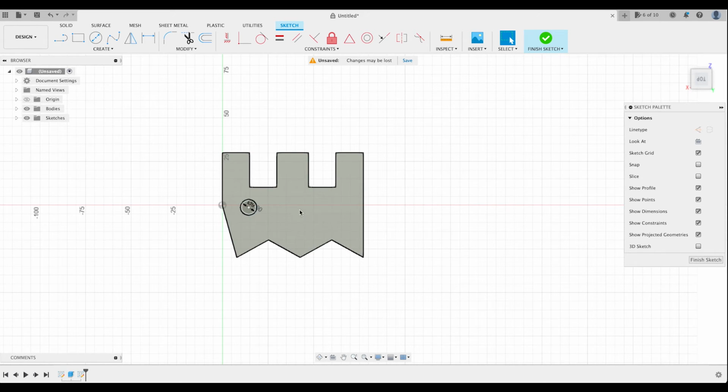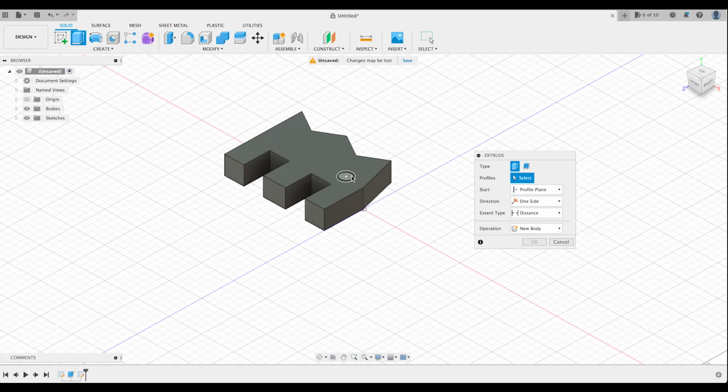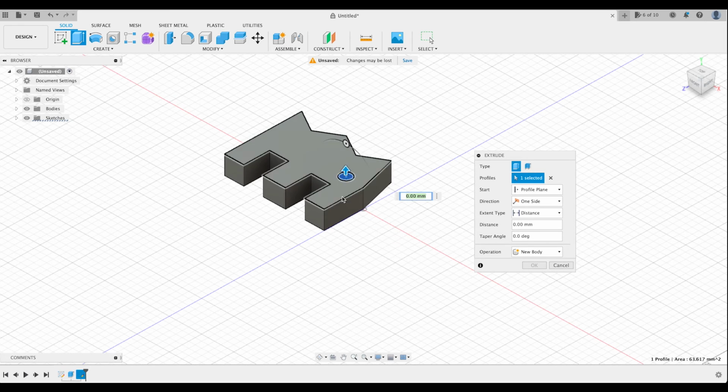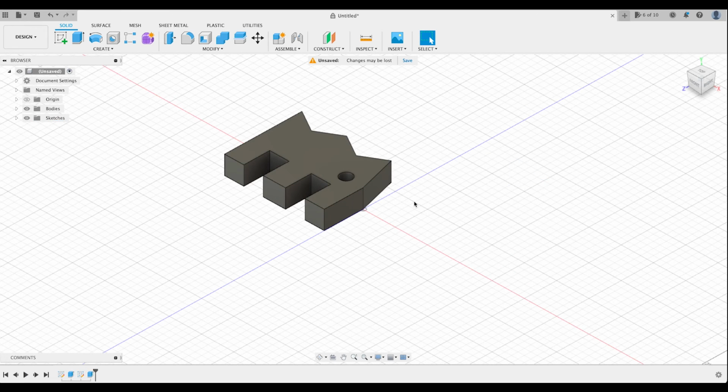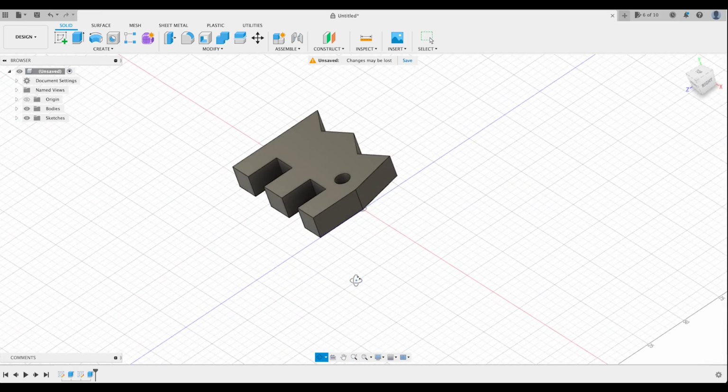and let's finish that sketch. Let's drill a hole through that. So I'm now going to E, extrude. And if you know the dimension of something, you can just drill through. So we know that was 15 millimeters, I think. So I want to make that a minus 15. It's all the way through. Let's just check on that. Yeah, it's gone all the way through.